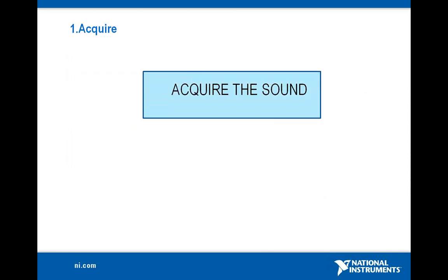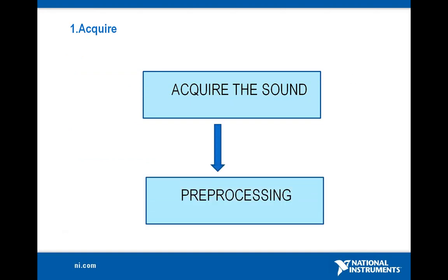In this particular application, we acquire the sound using an external microphone for a duration of 2 to 4 seconds with a resolution of 16 bits and a sampling rate of 20 kHz. The pre-processing that was used here involved steps like filtering the signal, making it appropriate for the consequent steps, as the signal as it is is not suitable for any analysis.